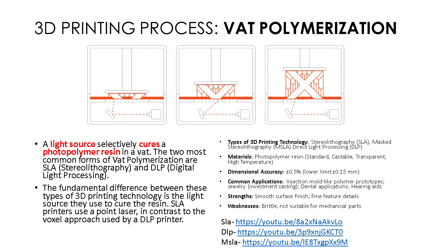Okay, and then next is vat polymerization. This one uses a selective light source. Some use light, some use laser. They shoot the laser into the liquid, a resin they call photopolymer resin. It's a liquid resin in the chamber. They shoot it, and the parts that the light touches on the resin will harden.